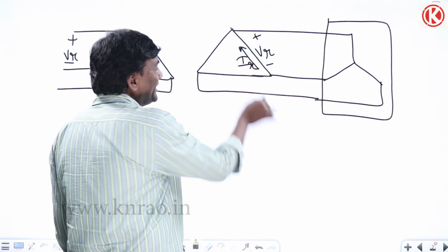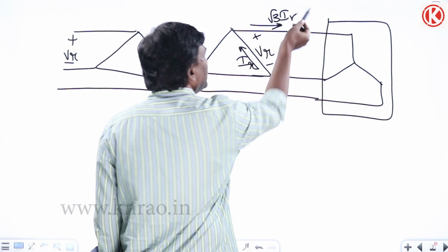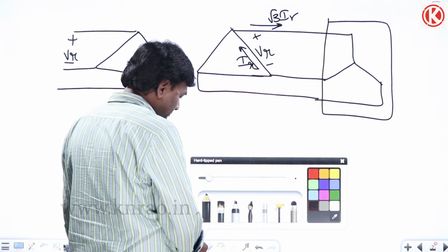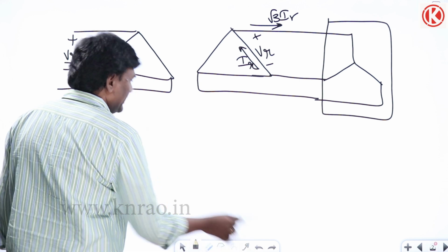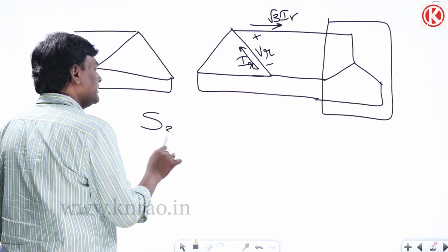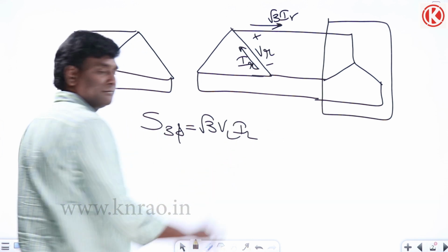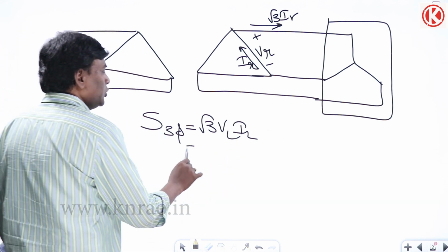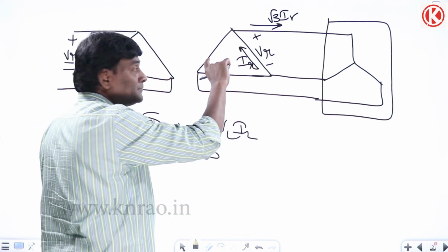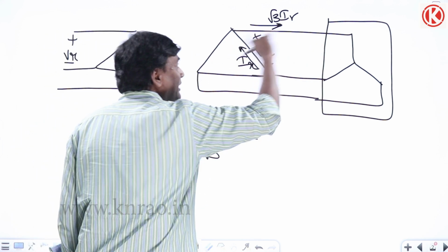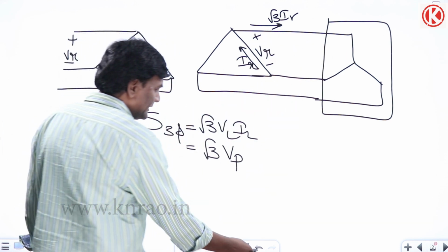Okay, so phase currents are rated, meaning that here the line current is going to be √3 times rated currents. In three phase, what is the power? Power in three phase, whether MVA or kVA, is going to be root 3 V_L I_L. Let me analyze: in delta connection, the phase voltage and line voltage are the same, V rated.